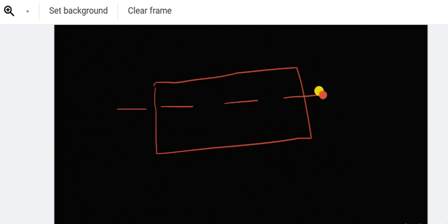Suppose, as we know, concrete is very weak in tensile stress, while at the same time it is good in compressive stress. So in the tensile zone we must insert a steel bar to increase the load capacity and to design a safe structure. So let's insert. This one is the tensile zone, and I have already explained why it is a tensile zone: when a load acts on the beam, the beam always resists bending, right?